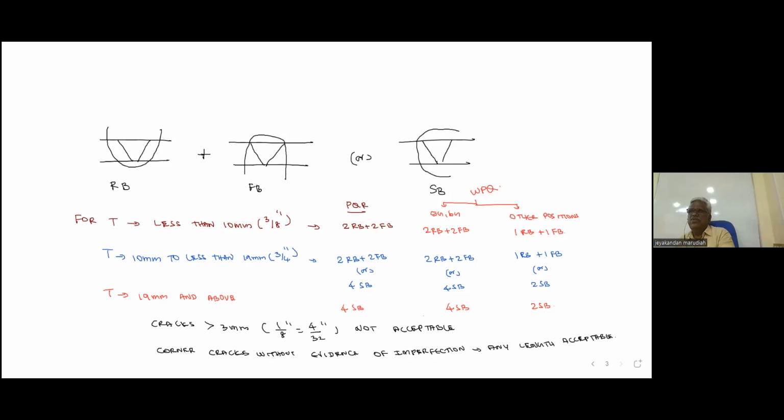Fourth difference is, what are the hardness tests? Brinell, Vickers, Rockwell, one more. There are 4 tests. We said 3. Brinell, Rockwell, and Vickers. Fourth one is called Knoop, K-N-O-O-P. There are 4 tests. What is the hardenability test? Jominy bar or Jominy end quench test. That is called a hardenability test. You should know these names.